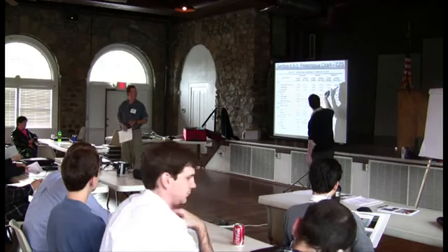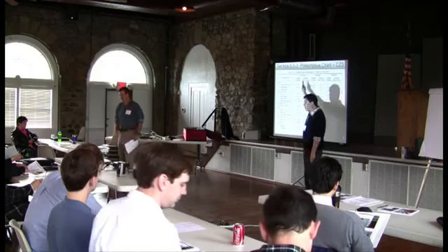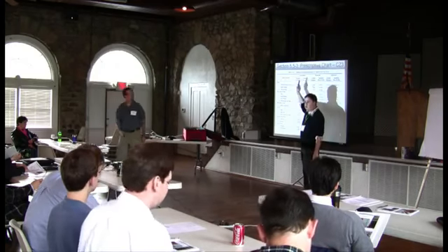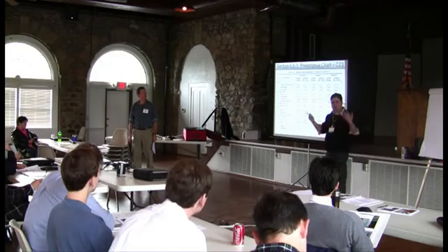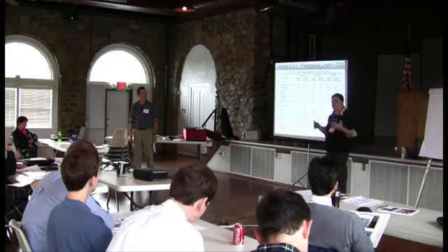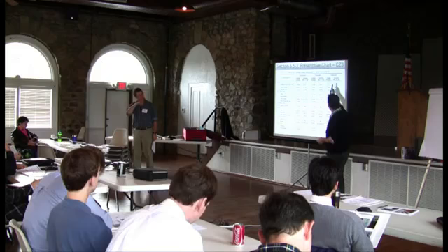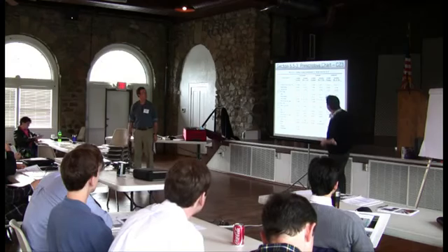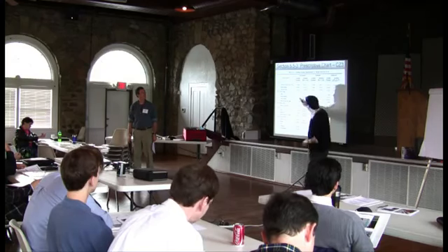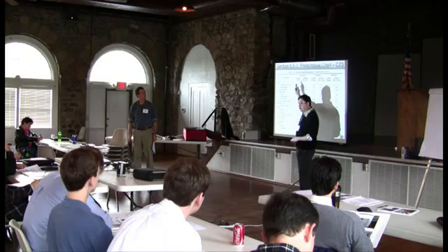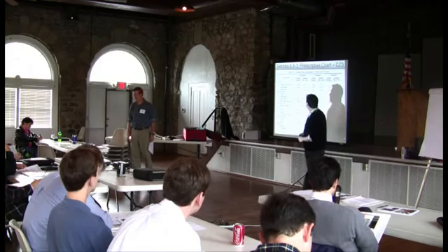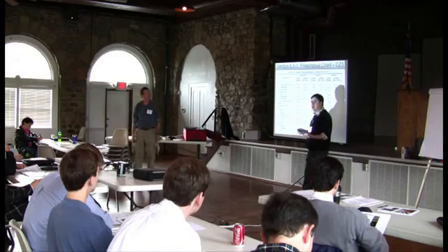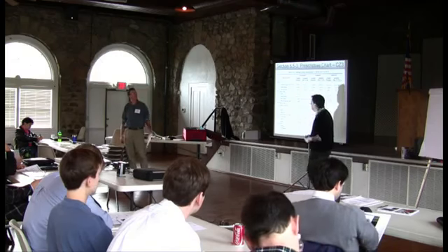And you'll see there's essentially three columns here. We've got the non-residential, the vast majority of the commercial buildings we're going to be dealing with. We've got residential. Again, those are multi-family, four stories and above, anything where people sort of stay overnight. And then finally, the semi-heated space. And you'll see what they're asking for. You can either look at it from an assembly perspective, a U value, a U factor, or you can look at it from just an insulation perspective, how much insulation from an R value perspective.